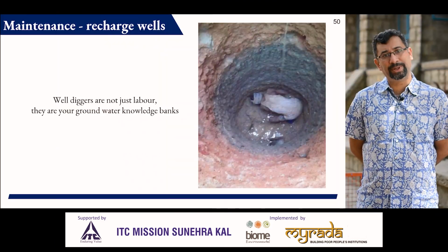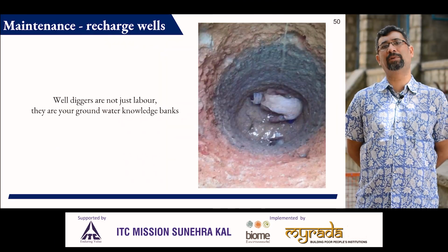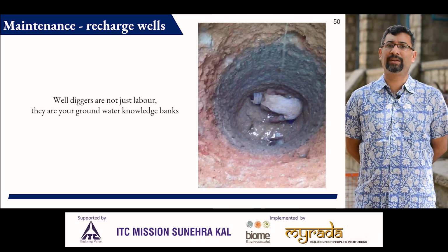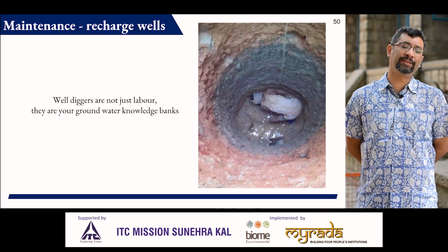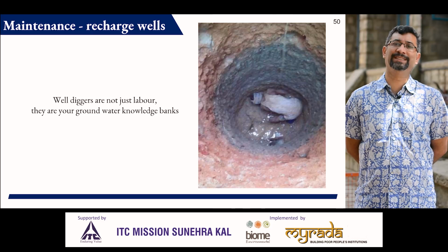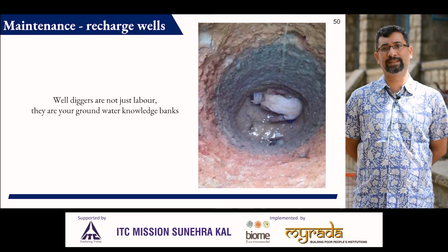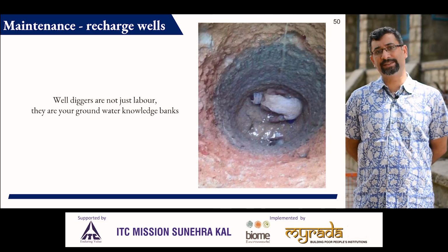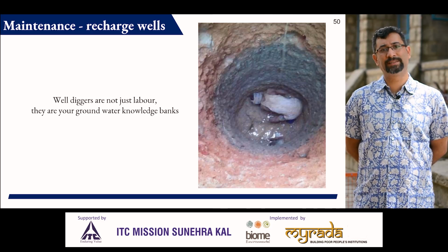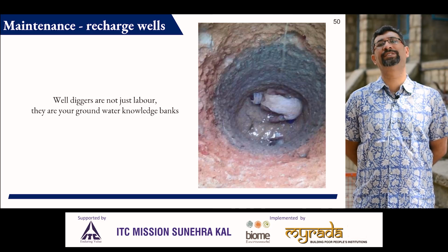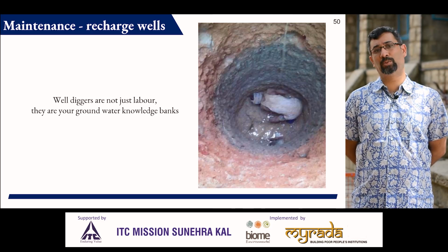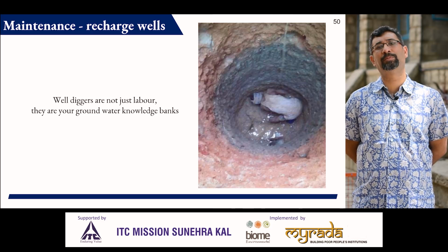Equally important in good management of your water systems is regular maintenance. Regular maintenance, for example, of your recharge wells, where you look at it once in 3 years to see if it needs desilting, if it needs some rings to be replaced. Here again, well diggers are going to be our partners, and remember that they are sources of knowledge. They can make observations to bring you insight into what's happening, and they are not just people who dig your wells.